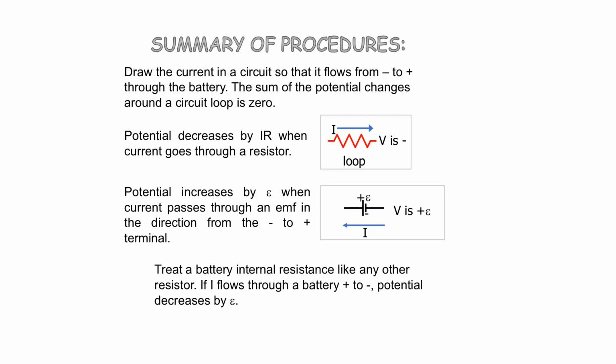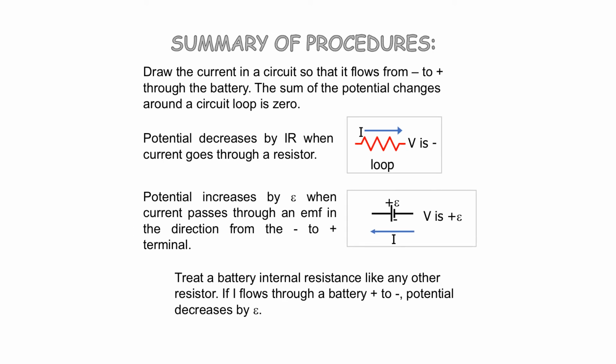So when it comes to EMF or back EMF, or we can say charging and discharging, the first thing you need to do is see the current flow, because when you see the current flow, you are going to detect whether it's charging or discharging. And if the question states terminal voltage, you only focus on the battery or power supply. If the question states an ideal battery or power supply, it means there is no internal resistance.